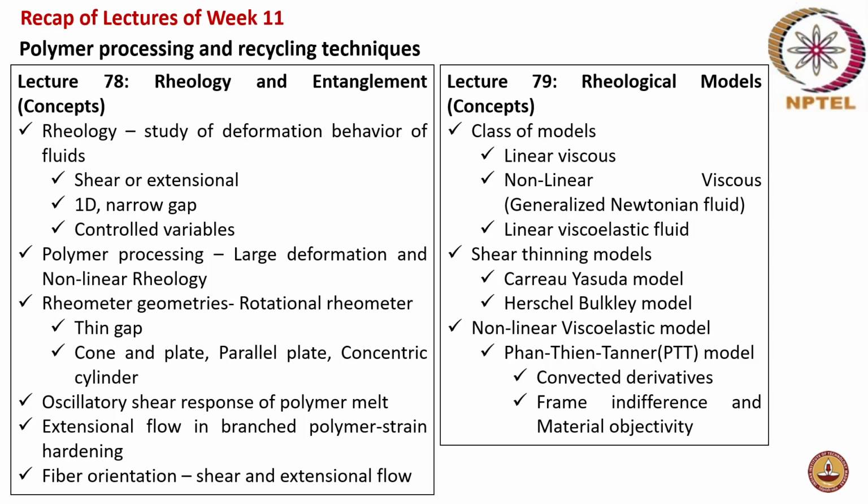Okay, and then linear viscoelastic fluid model was discussed, and then there was a discussion on shear thinning models. Here there was a discussion on the Carreau-Yasuda model for polymer melts and polymer solutions, and then the Herschel-Bulkley model, which is nothing but a yield stress fluid model. Next, there was a brief discussion on non-linear viscoelastic models. The Phan-Thien Tanner model was discussed here. The convected derivatives, frame indifference, and concept of material objectivity, these were all discussed.